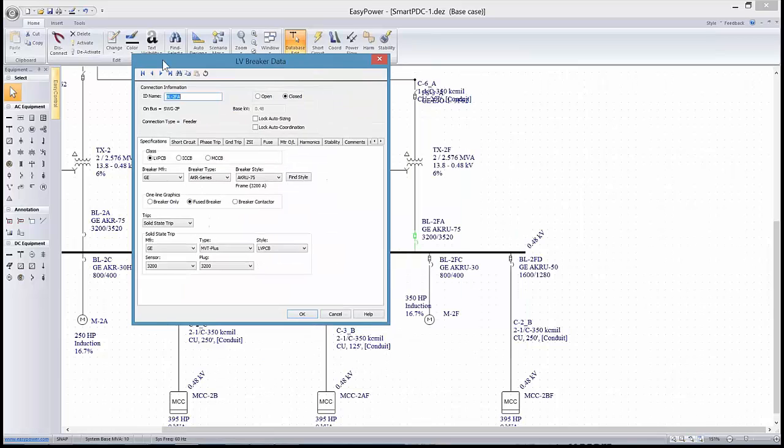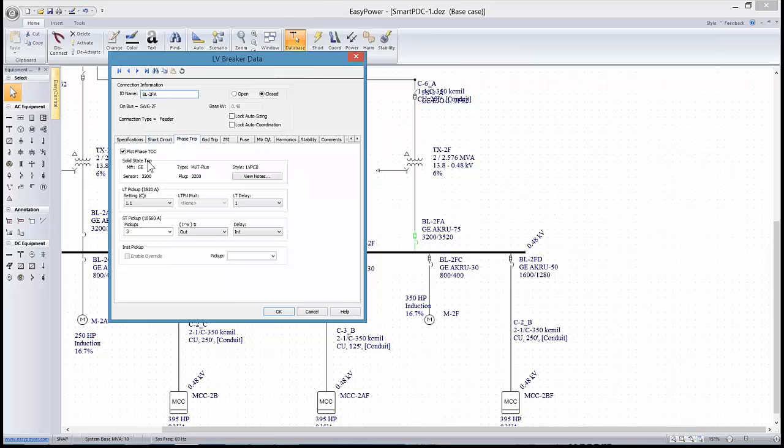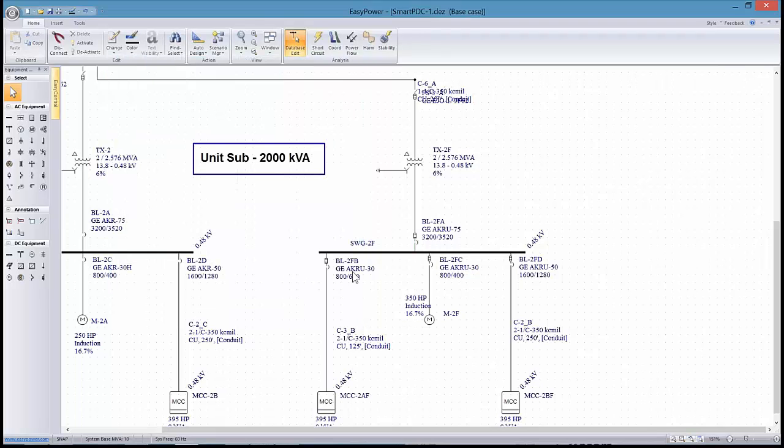And most of the time when we receive a file and someone says, okay, I'm trying to do my first arc flash study and all I get is no protective device installed, it's because they haven't fleshed out the details of each of the breakers in line with that particular load, and most importantly, they haven't specified what the trip settings are for overcurrent phase voltage or phase current. And so we'll get into more of that, the principles of coordination, starting next week.